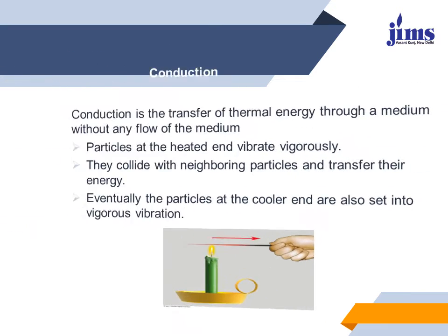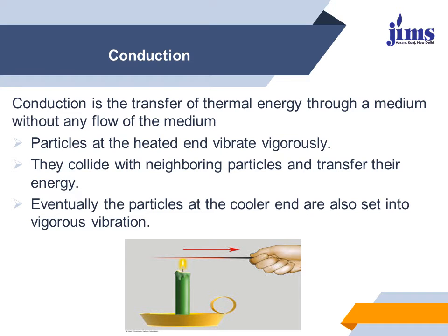Now conduction. We can define conduction as the transfer of heat through a medium without any flow of the medium. Particles at the heated end vibrate randomly. They collide with neighboring particles and transfer their energy, and eventually the particles at the cooler end are also set into random vibration. In this diagram we can see that when we heat a metal, the heat transfer takes place from one part of the body to another part of the body due to the temperature gradient.